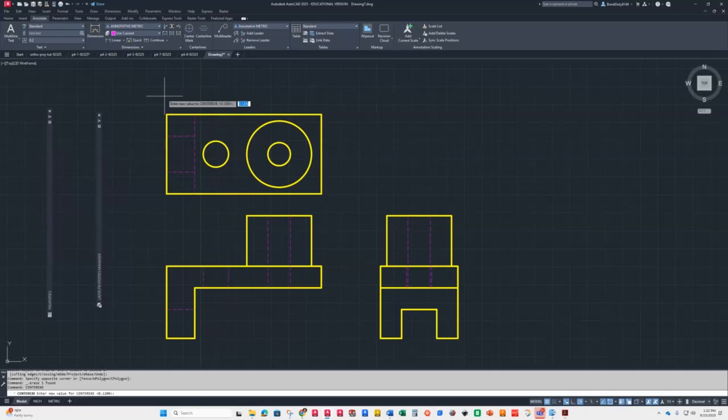So what is the equivalency from 1/8 to metric? Well, if you do the math, if you take 0.125 and you multiply it by 25.4, you should get 3. Probably 0.12 will give you something less than that. But anyway, 0.125 converted to metric is 3, or that's what we use for it. So depending on what your scale is, you're going to make it 3. If you think it's going to be a half scale, you make it 6.